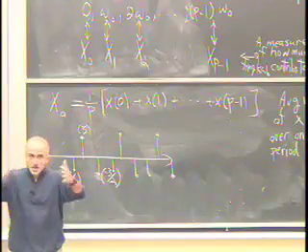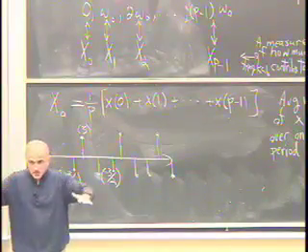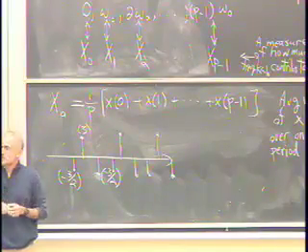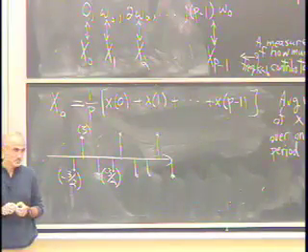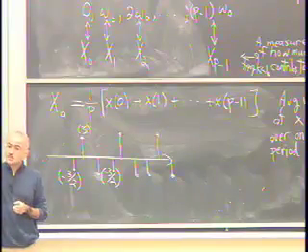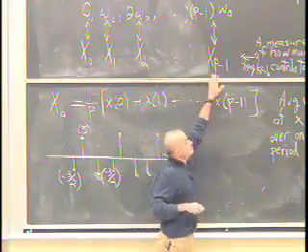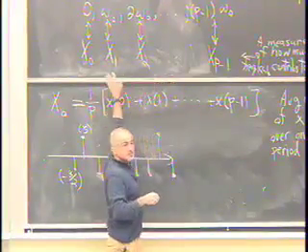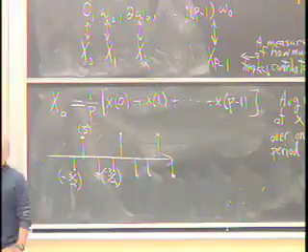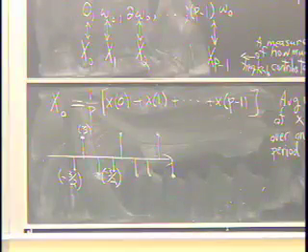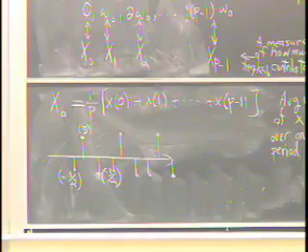As you go higher in frequencies, the contributions of those frequency components decrease, and so it's a relatively smooth signal. The faster the signal varies, the larger the magnitudes of the higher coefficients and the smaller the values of the lower coefficients. So there's a direct relationship between how the signal behaves in the time domain, along the n-axis, and what those frequency coefficients tell you.